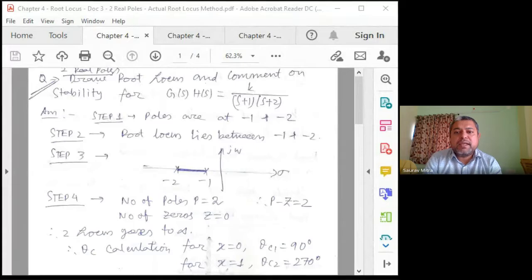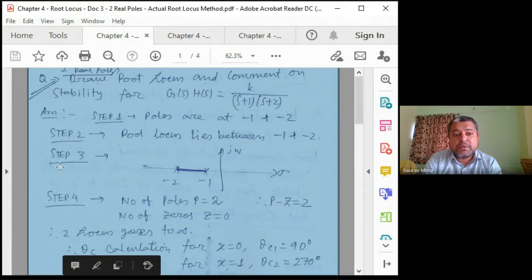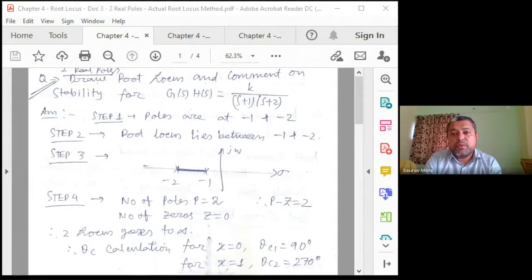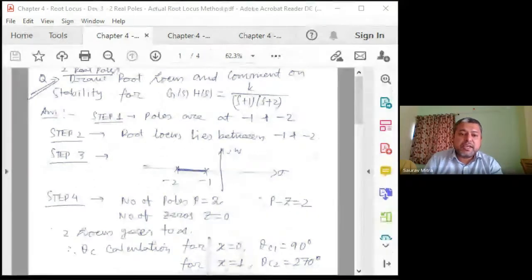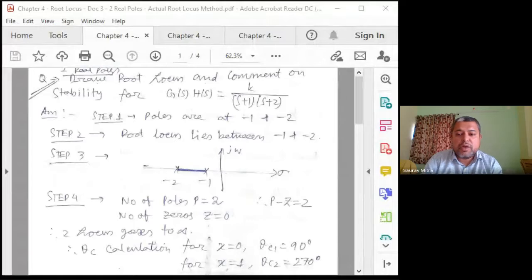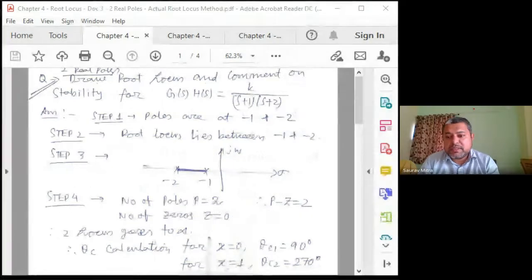And we had found that at k equal to exactly 4, both these two poles were hitting each other exactly at s equal to -2. So we are actually checking the position of the poles on the real axis on the left hand side of the S plane with the increasing value of k. At k equal to 0, poles were at 0 and -4.